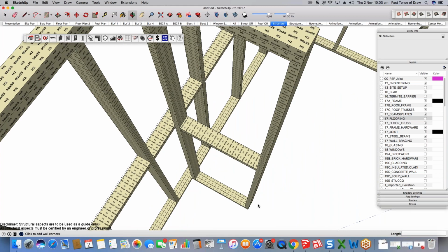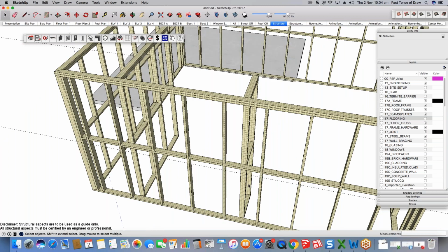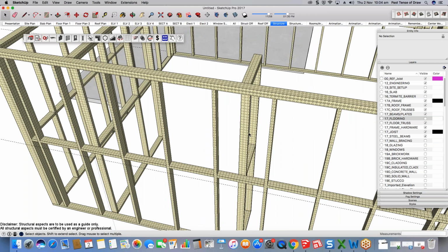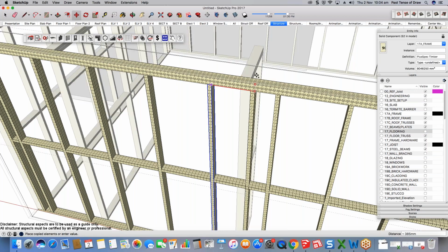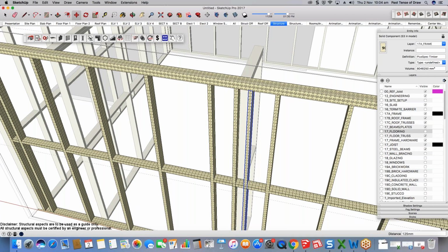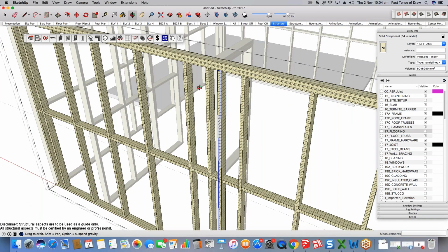Now, like the joists, if you really needed to add additional items in here for your wall structure, that's what the beam post is really good for. I'm not going to get into the beam, I'm just going to show you manually, but you have the ability to grab or create your beam tool and align it with the internal, so you're connecting it how you need to. Because you're drawing it with the beam tool, if you do make a change to the wall, it doesn't matter because your structure will be there. But that's the advantage of going into your different scenes, particularly the structure scene.